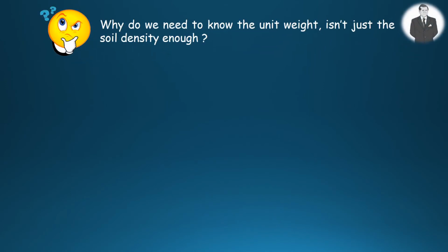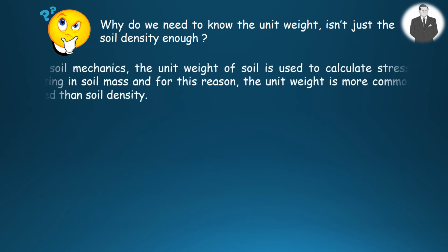The question is, why do we need to know the unit weight? Isn't just the soil density enough? Well, in soil mechanics, the unit weight of soil is employed to calculate stresses acting in soil mass, and therefore the unit weight is more commonly used than soil density.